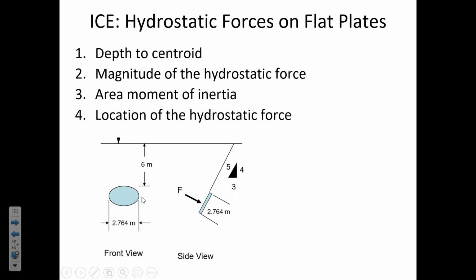And I've given you the step-by-step. Step 1, depth to the centroid. 2, magnitude of the force. 3, area moment of inertia. 4, location of the hydrostatic force.